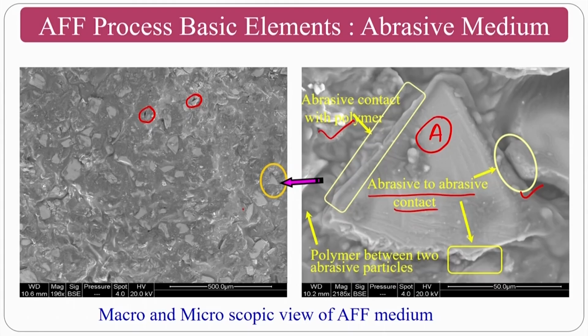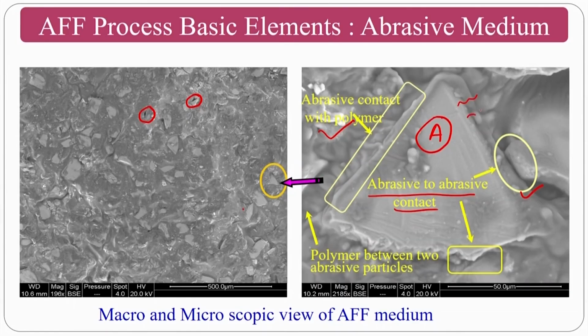Many people think about how the abrasive particles, which are solid particles, will stay inside the abrasive polymer rheological complex medium. Polymer is semi-solid to solid or semi-solid to liquid. Rheological additives are mostly liquids, but you have semi-solids or powders also. In this particular complex, where are the abrasive particles sitting? That is one of the biggest challenges to understand. Commonly, the polymer network dimensions are approximately nanometers, but your abrasive particles are approximately 50 microns to 100 microns. So how will it work? Normally your polymer networks will be there, which are bound, and at the same time you use rheological additives to hold it.